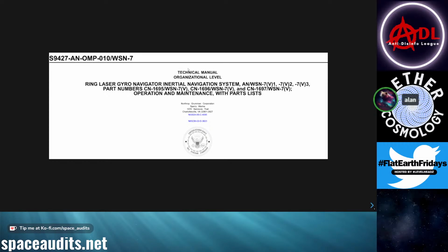Before we get into that, I didn't have time to put this in the presentation, but we'll cover quickly what happens when you boot this device up, because a lot of people think that you just turn this bad boy on and it starts telling you that the Earth's spinning and all this stuff. It's a little more complicated than that. When you first start the device, you have to input your relevant coordinate systems, lat long, based on whatever map references you need. It also takes input from GPS coordinates, so it takes a multitude of different points of data to put you on the coordinate system and get your location on there.